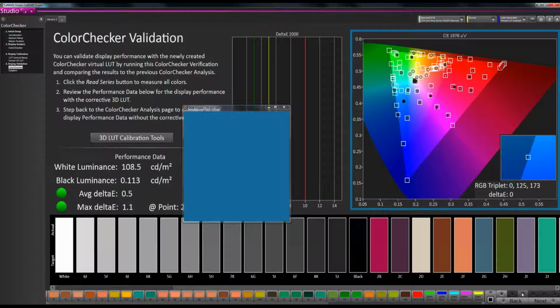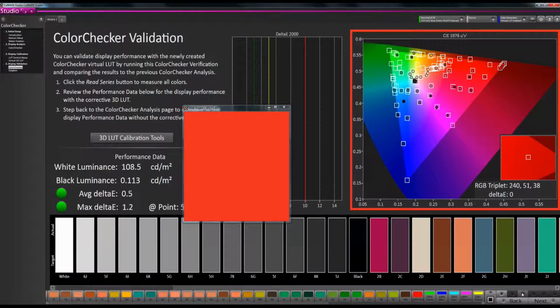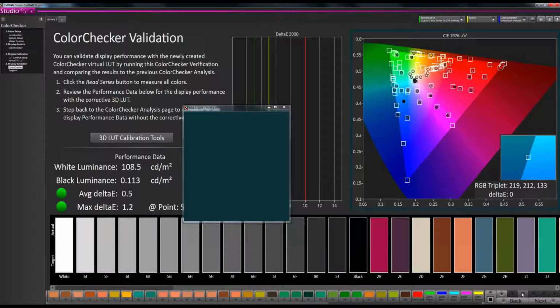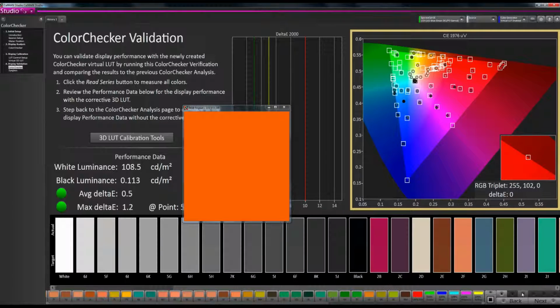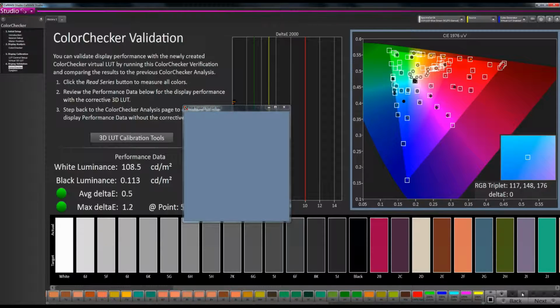So what about those of the people out there that still use a gamma formula like 2.2 power or 2.4? Can you still do this in CalMAN? Yes, essentially you would just go into the gamma formula setting in CalMAN settings, the gear wheel, and pick power law, and then enter your target exponent of 2.2 or 2.4. A lot of people do this if they're working on a legacy project that was originally mastered with something that was calibrated to 2.2. Okay, that makes a lot of sense.